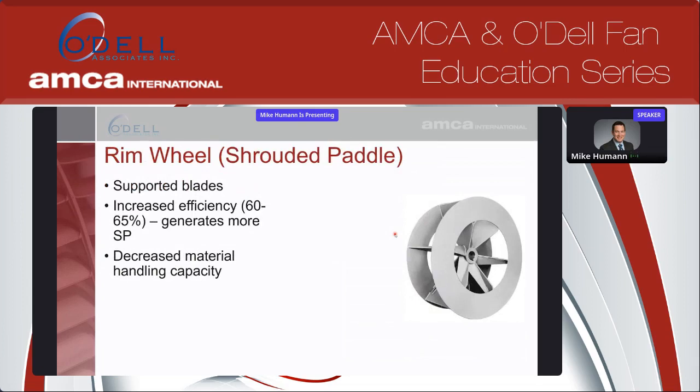Similar style wheel, it's basically the straight radial wheel with a couple rims on it, or front and back shrouds. So with this wheel, you get a little bit more efficiency out of it because of the ability of the shrouds to generate some better efficiencies and higher static pressures. So you'll see that, but you also lose some ability to handle material. Things can get stuck, hung up on the rims if you have stringy material. So there's a trade-off there for that efficiency gain. You lose the material handling capability for any application.